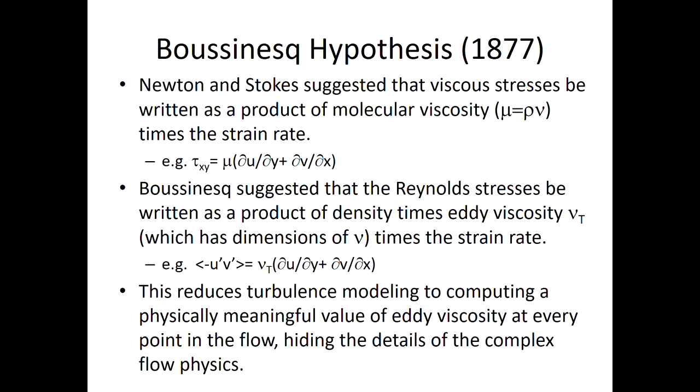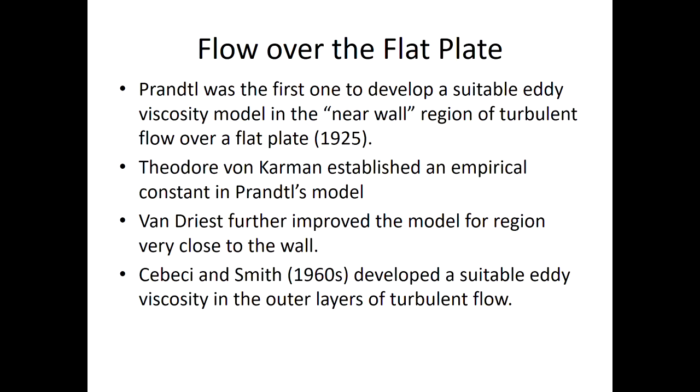So in a CFD computer program like Fluent, they will first compute this eddy viscosity, then multiply by the mean flow velocity gradient, just as we take the molecular viscosity multiplied by the mean flow velocity gradient. As simple as that. So the problem becomes, how do I find this eddy viscosity, nu t? Boussinesq didn't give any idea. He kind of stopped at that point.